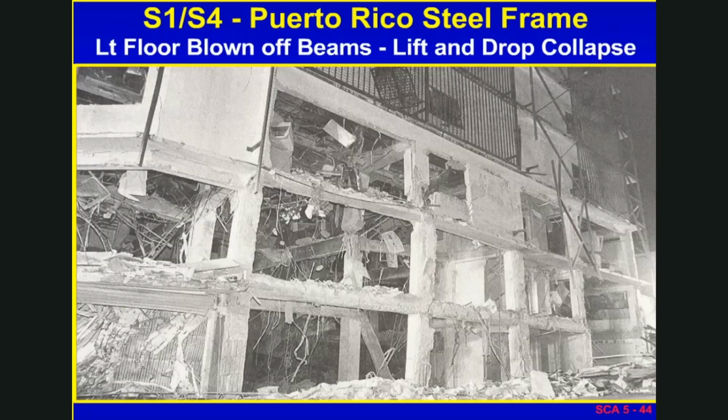This is a building from Puerto Rico. It actually is a concrete exterior frame, but the steel framing of the interior. And what happened in this case is that the floors were very light bar joist with light steel deck and a little bit of concrete fill, and all the floors were thrown up into the air, and they all ended up in the basement. So if you think about that, the survivability of the people that were on those floors has got to be very, very low, and in this case, no one survived.